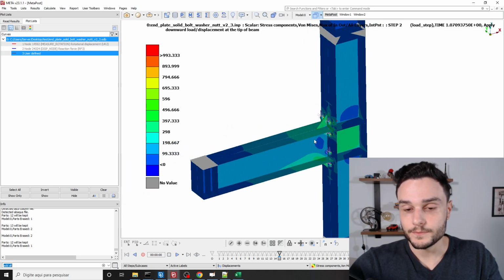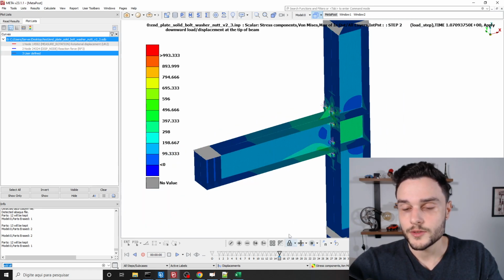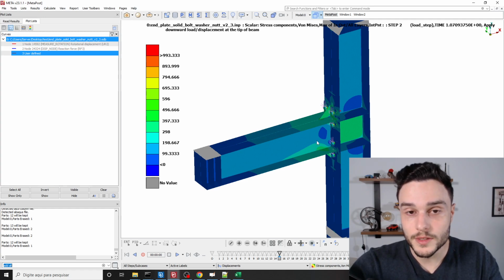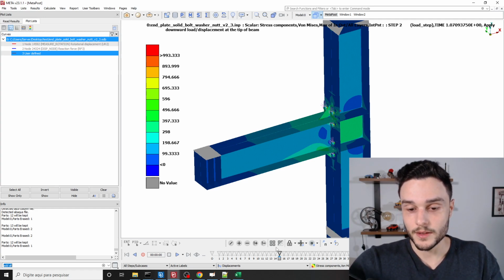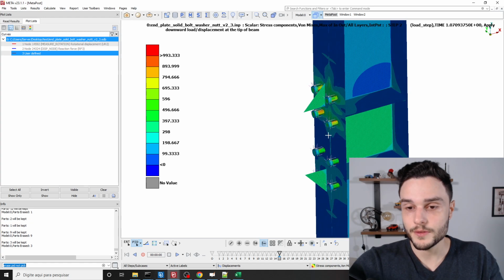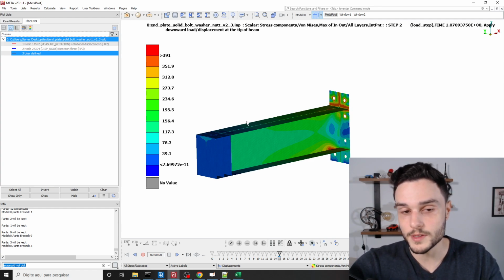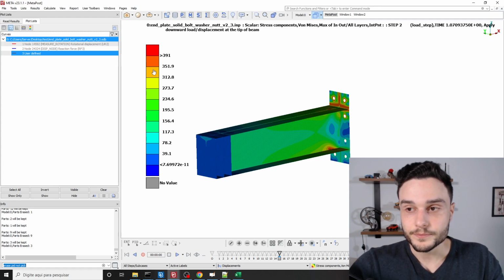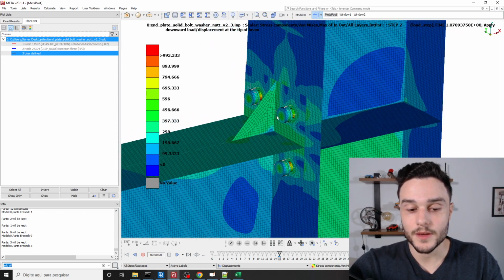Well, you can perform the same kind of analysis of stress for the other components to see. You can establish the acceptance criteria, if it's yielding, and then you can isolate, for example, the beam with the end plate, and then you can analyze what is the displacement that we can have so that we don't have yielding occurring. For example, you can perform this kind of analysis.